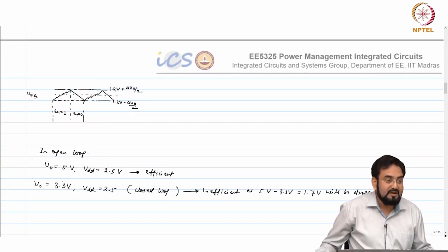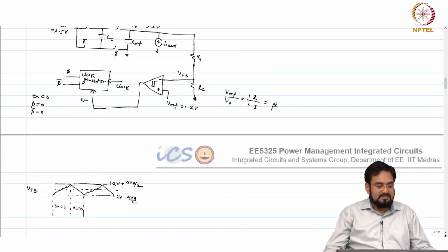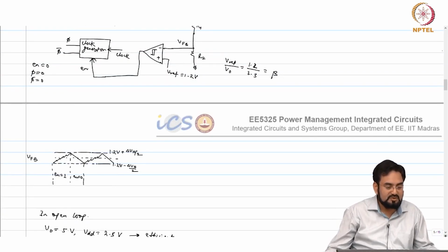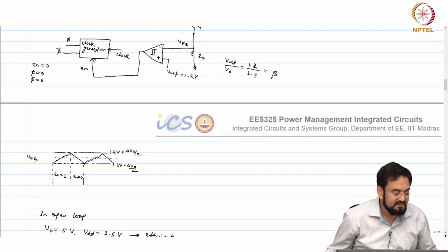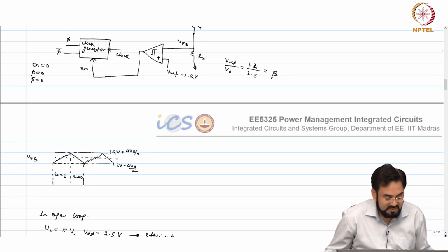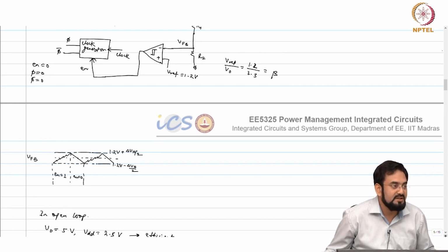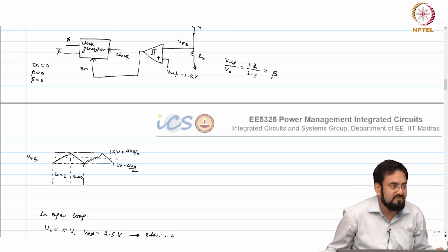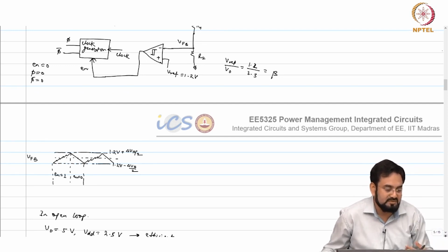But if you look at a light load condition, with this hysteretic converter, the output is discharging, so switching losses will automatically scale with your load, because the frequency will start reducing. You charge and then you wait until your load discharges. As your capacitor is the same and your load is reduced, your discharge rate will be slower, so next time you will be switching later. It is more like a burst kind of operation, so we call it burst mode also.